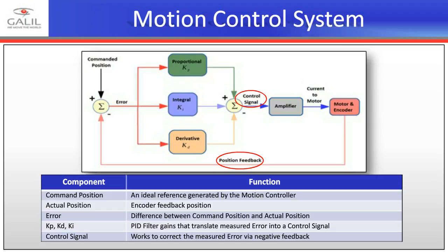Low cost due to a variety of sizes, ratings, and vendors. There's quite a competitive market out there. And extremely low latency. The signals produced by the controller and encoder are essentially seen instantly. As soon as the motion controller puts out that 10 volt signal, the amplifier sees it on the wire as fast as the electrons can move, which is pretty fast.